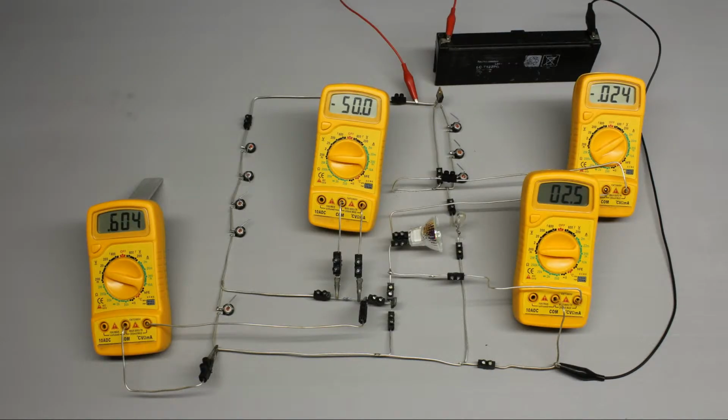While recording the curve progression of current versus voltage at the transistor's collector pin, the current running through the base pin has to be kept at a constant level.